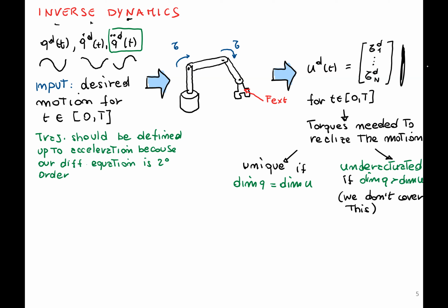We will briefly define next week, I think, what underactuation is. Underactuation is whenever we have a bigger number of degrees of freedom than the number of degrees of freedom that are actuated. So there are some degrees of freedom that are not actuated. Think about, for example, a legged robot standing on his legs, and his base, so his trunk, represents 6 degrees of freedom that are underactuated.